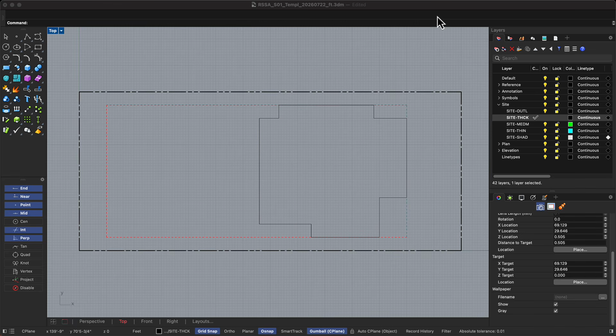Now, the ADU footprint. We're not designing the building yet. That comes in later episodes. So at this stage, it's simply a rectangle marking a preliminary location. It's also a good moment to show a precise way to enter dimensions, relative coordinates. Start the rectangle command and pick a point for the lower left corner over in the western end of the lot. Then, instead of clicking the opposite corner, type R 26 feet, 40 feet, and press enter.